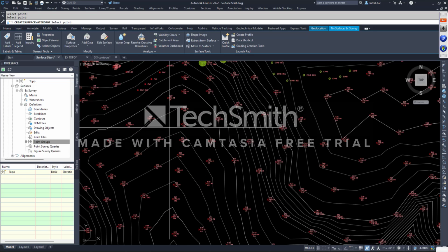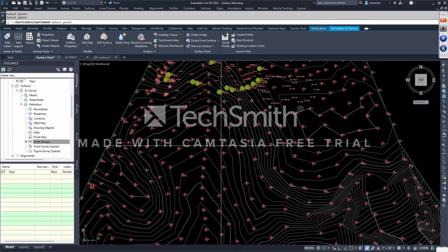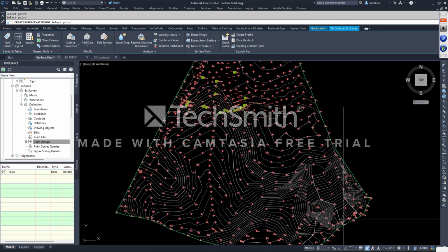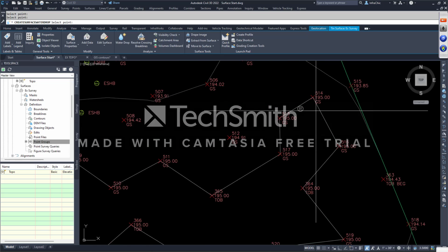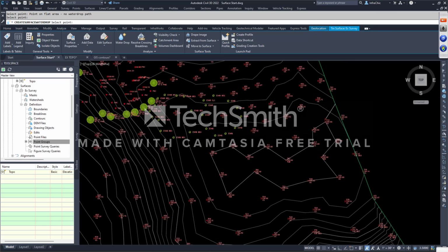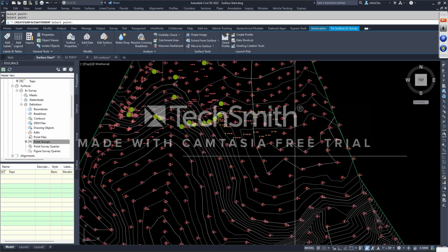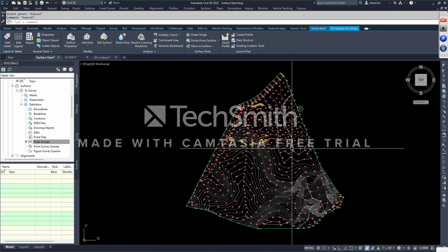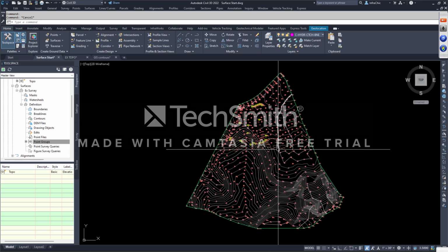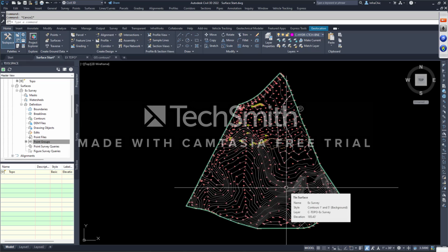So why would I need this? As a civil designer, I need to know the time of concentration. That's the water drop path, the time of concentration. And that's why you as a surveyor need to make sure that this is reflecting what's out in the field, because we're going to have to do this little water drop routine that I'm doing right here. And I'm going to have to go over here, and at one point, one of these lines is going to be super long, and that's the line I've got to use and everything else goes by. But it's all dependent and based upon this surface and how it's reflected.